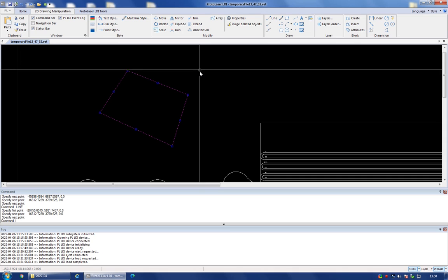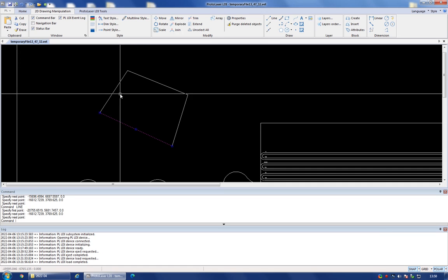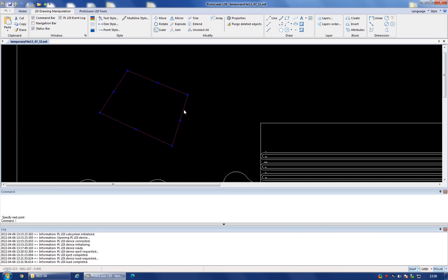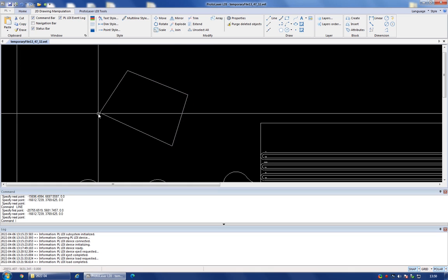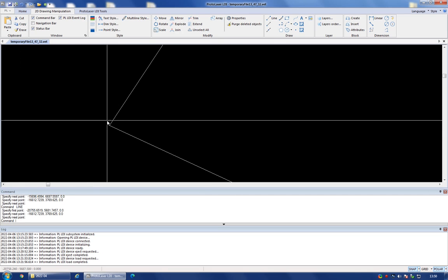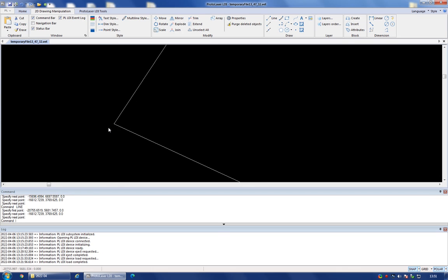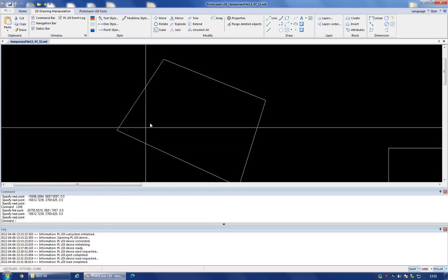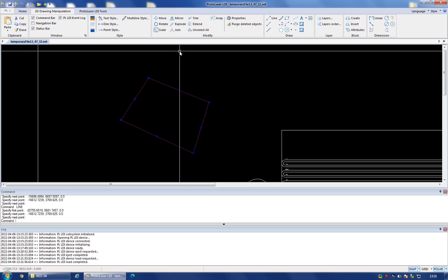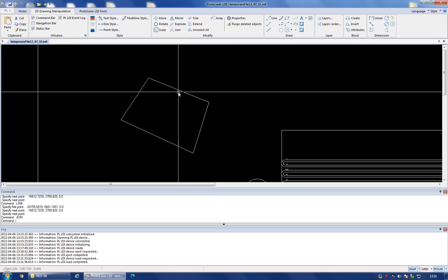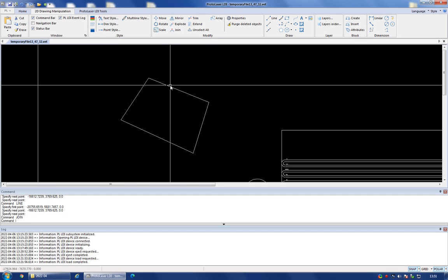And now you can actually see that this shape that I've drawn is a collection of 4 lines. This is not a single line, but a collection of 4 lines that just happen to start and end in the right places. So you see that as much as I zoom in, these lines will terminate exactly in the same point. This is what you want, but to make sure of this, you can select an enclosed shape and hit the join button, and this will make sure that all the lines you have selected inside your shape actually belong to a single shape.